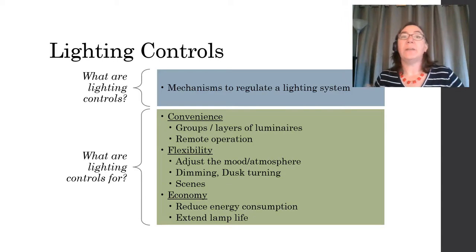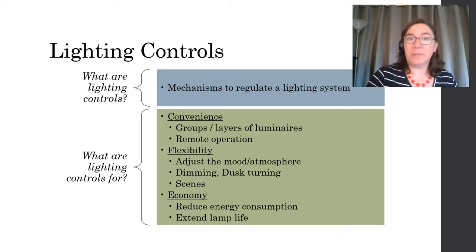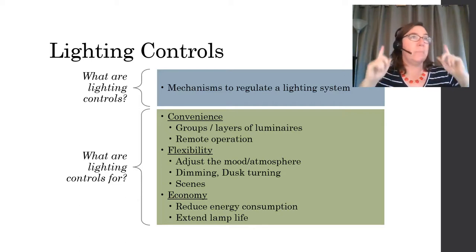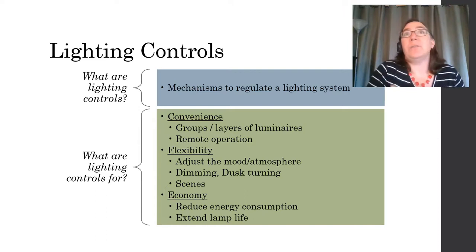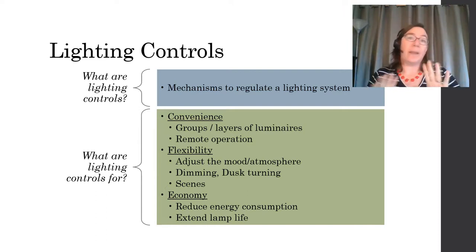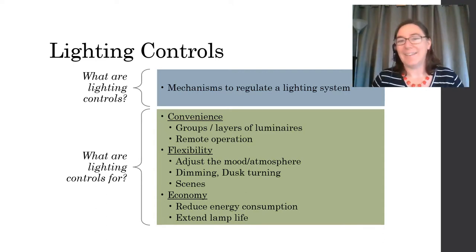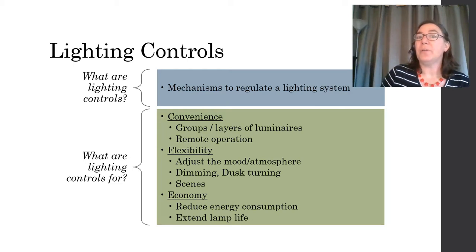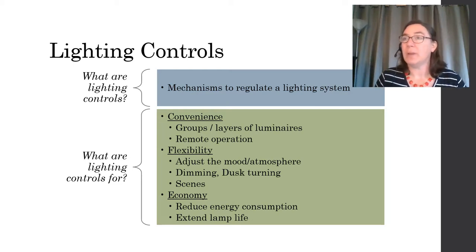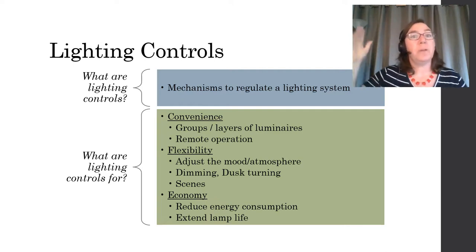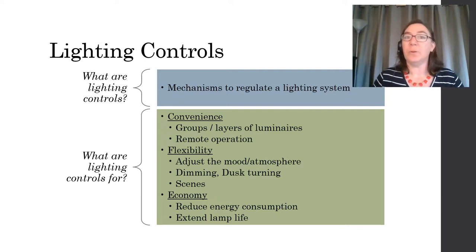All right. Also, we like to control layers of lighting with individual switches, or controls, rather than remembering, okay, I would like to turn on the ambient light now only. I don't need this task light over here, so I should turn on these three luminaires. Also, controls are good for remote operation. It's much more convenient as you step into the room to touch the light switch that is next to the door than to wander through a dark space and attempt to find the control maybe mounted on the luminaire.